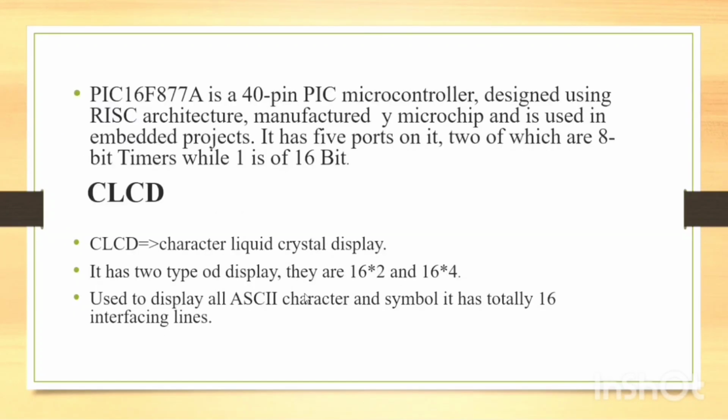The PIC16F877A microcontroller is a 40-pin microcontroller designed using RISC architecture, manufactured by Microchip and used in embedded projects. It has 5 ports, two 8-bit timers and one 16-bit timer. Here it is an 8-bit microcontroller.